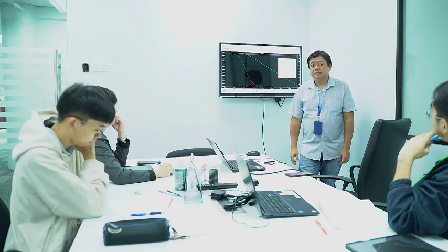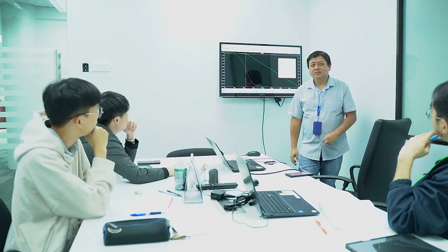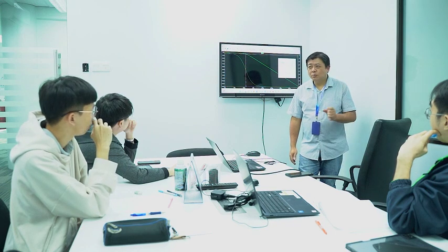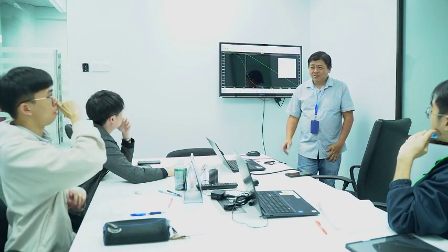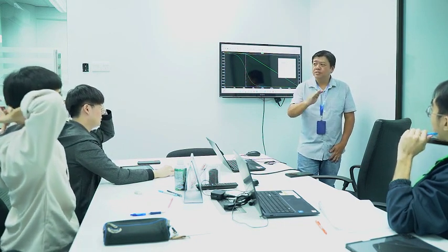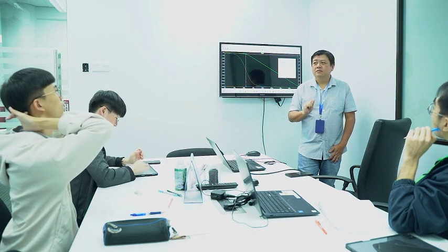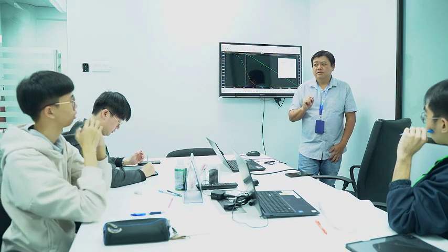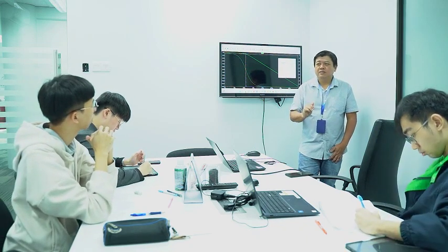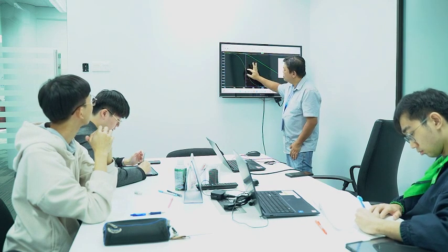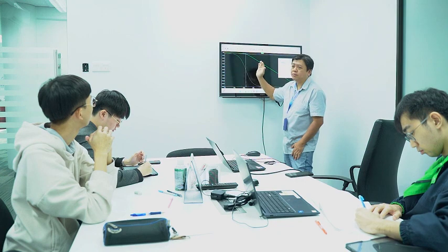In the time domain, we call it propagation delay. Phase shift tells you the information about the delay between your input signal and output signal. So how much the phase shift is at a certain frequency, at your input frequency, will tell you how much the delay is between your input and output.